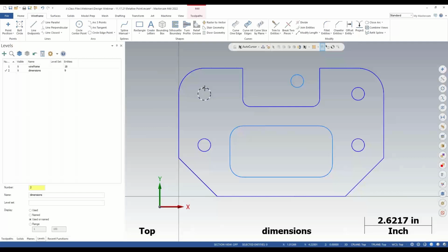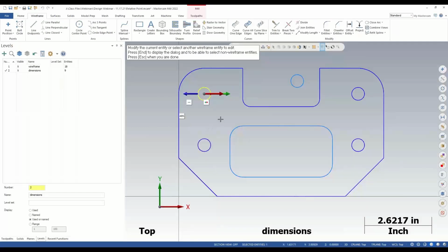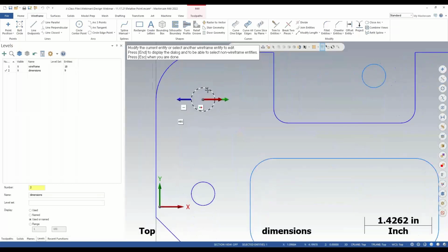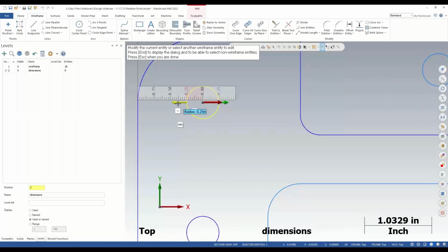And I can double click on this arc, and that gives me a bunch of on-screen controls. First being the radius. So this blue arrow right here is determining my radius. So in this case, it's saying it's a 1/4 inch radius, but I can click on this arrow and I can expand it, contract it, expand it, contract it. And again, if I'm off the ruler, it's wherever it is in space. If I'm on the ruler, it's incremented. And of course, like I said before, I can actually type something in.